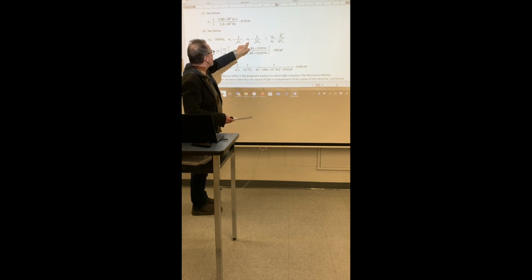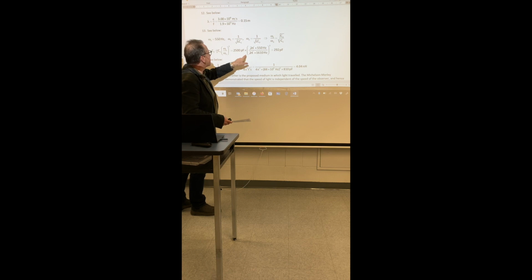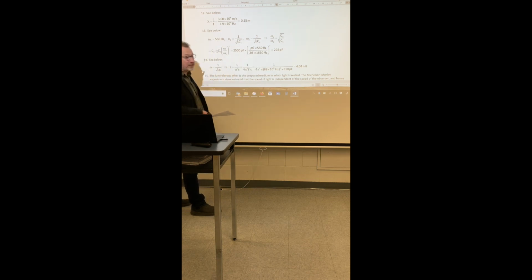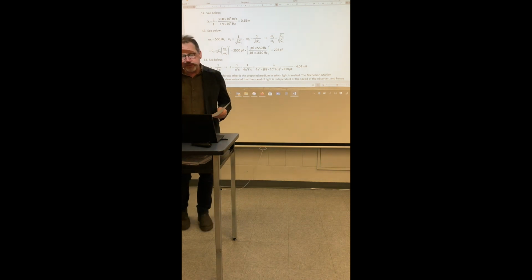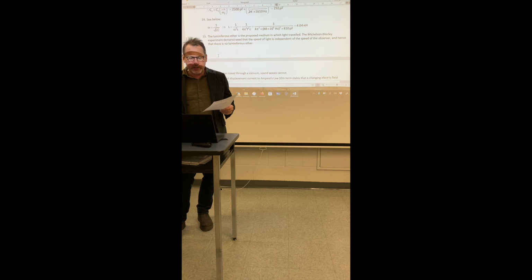If I do that, you can see that the inductance cancels out, and I can just express C2 as the ratio of the frequencies squared divided by C1. This is omega, which is 2 pi f, but of course I can cancel my 2 pi's out, so it simplifies down to this expression here, and there it is, 292 picofarads. Okay, so a simple question. Try and solve it elegantly, and don't bother working out the inductance. Right, it's easier than that.